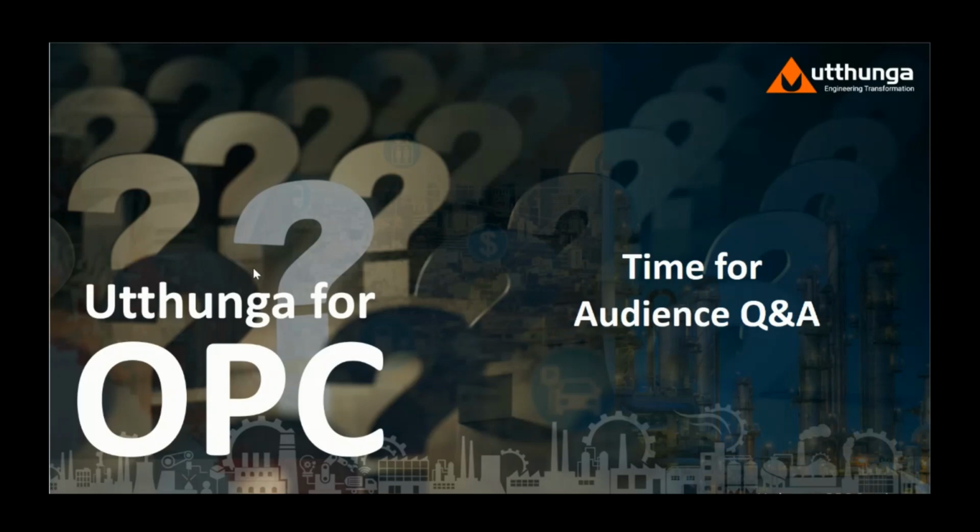Okay, one final question, just before we run out of time. How much old historical data can be accessed using OPC UA? This is from Samir Sani. So there is no actual theoretical limitation. It depends on what your database size is and how far back you have stored your history into your HDA. So once you raise the request, even if the response size is huge, OPC UA can still chunk it out into smaller records, and it will keep sending it.